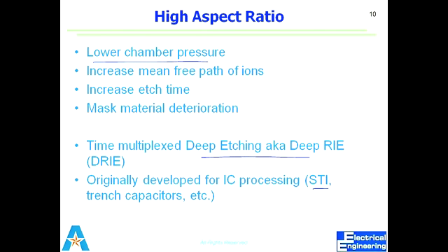I mean, is it predefined that for this energy my mean free path will be this amount? Yeah, if you're talking about the etching process, you don't need to know the mean free path of the etching species that I am using. These are not the parameters that you consider when finding out the etch rate. These are in the background, what is going on. I am just explaining to help you understand. While etching with the equipment, you just need to know what voltage and what pressure you should supply. So you define the recipe based upon those.